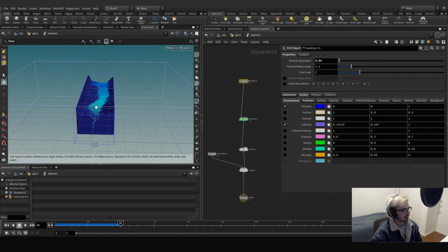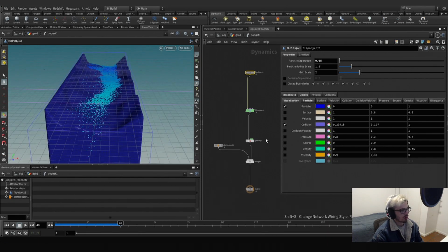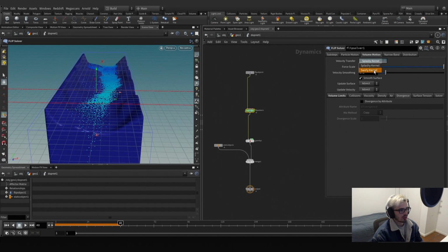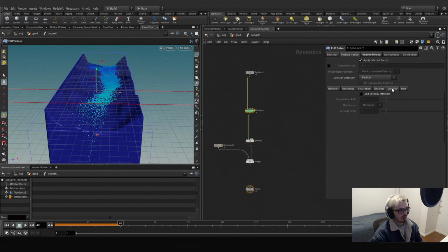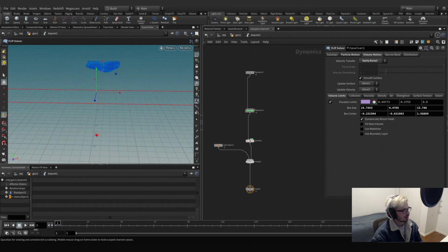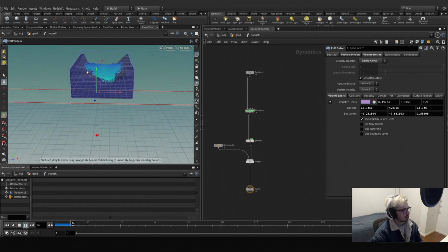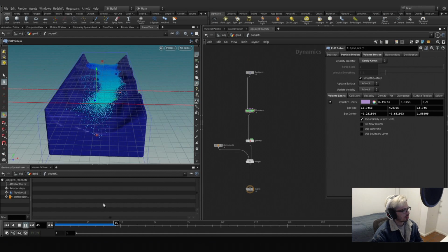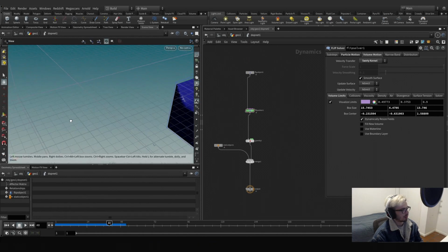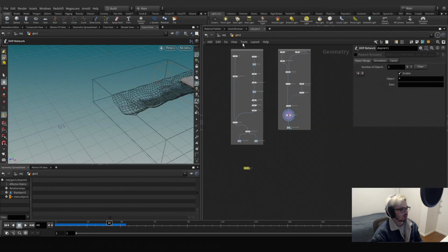So this is a really optimized scene. So let's improve this a little bit. We need to plug this into swirl kernel. We need some vorticity. We need some rest. This set to 25. Remember, we are not going to cover shading, but you will probably need this in every situation. Let's add a little bit of particle separation. 1.2 will do. And this should be it. Let's see how this looks or behaves now. This is a little bit thicker, and overall I'm really liking how this looks, as for being a low res simulation. So let's move forwards.